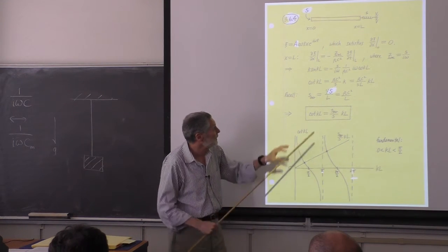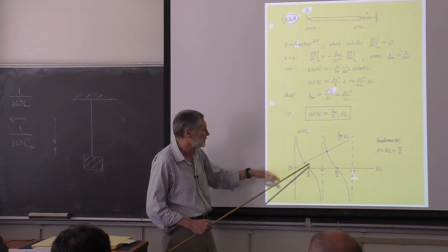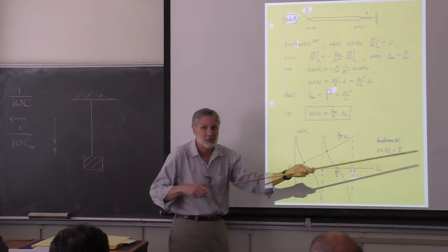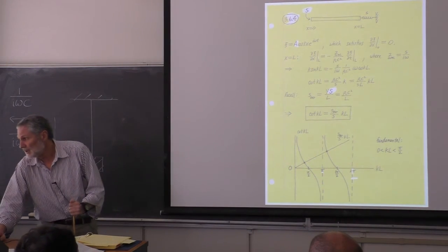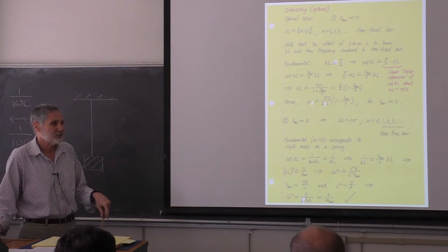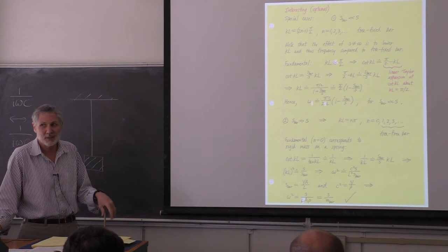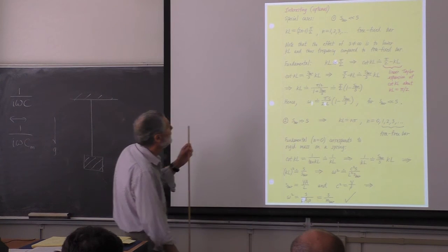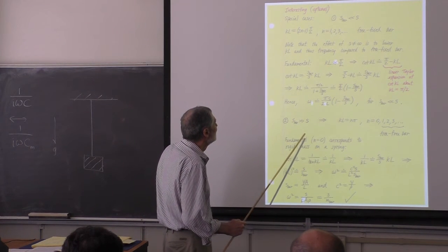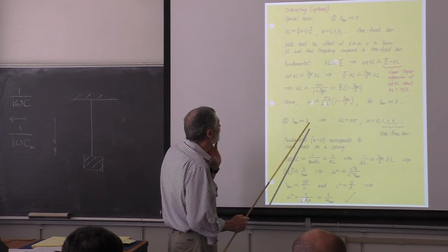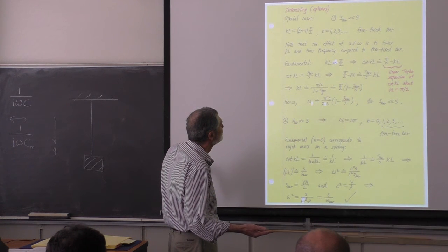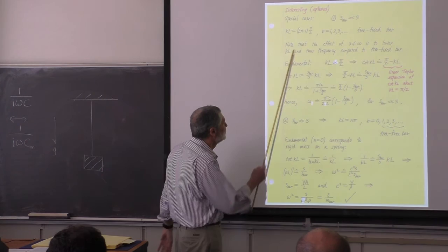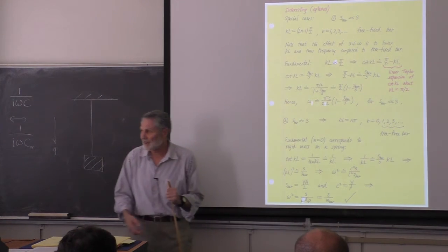On a scale like this with motion, longitudinal waves in here, it is close to 0, with this thing just going back and forth like a rigid mass. That's relatively very low frequency. But you can get the result out. And the result has to be that the frequency is the square root of the stiffness divided by the mass of the bar. So you eventually get it out. Well, you can check this, and if you have any questions you can ask me.